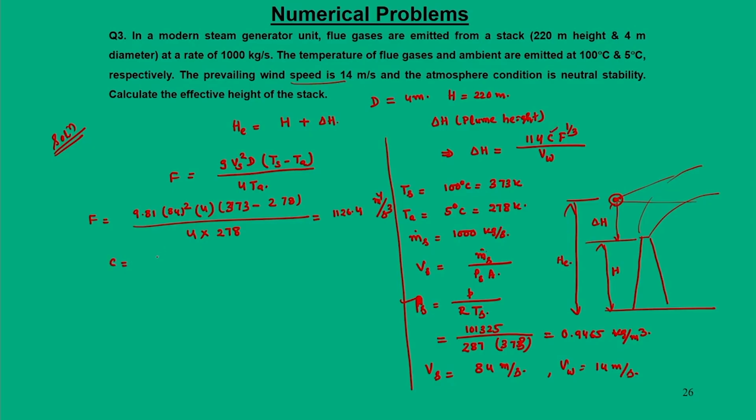C is nothing but a non-dimensional term given by the expression 1.58 minus 41.4 delta theta by delta z. Delta theta by delta z value, let us approximate to a value of 0.005 for atmospheric stability conditions. Now, when you assume this value, C is equal to 1.373. So, essentially speaking, in this equation we have all the parameters.